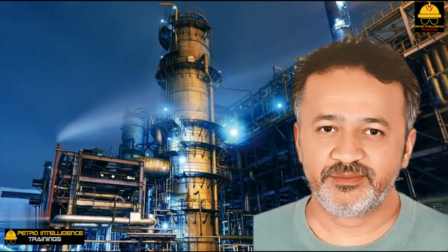What is air lock? Vapor binding, or air lock, is another common cause of household radiator malfunction. Often, the vapor accumulating in the radiator is CO2, rather than air. The CO2 originates from the thermal decomposition of carbonates in the boiler. Regardless, air and CO2 form a non-condensable vapor in the radiator. These non-condensables mix with the steam in the radiator.